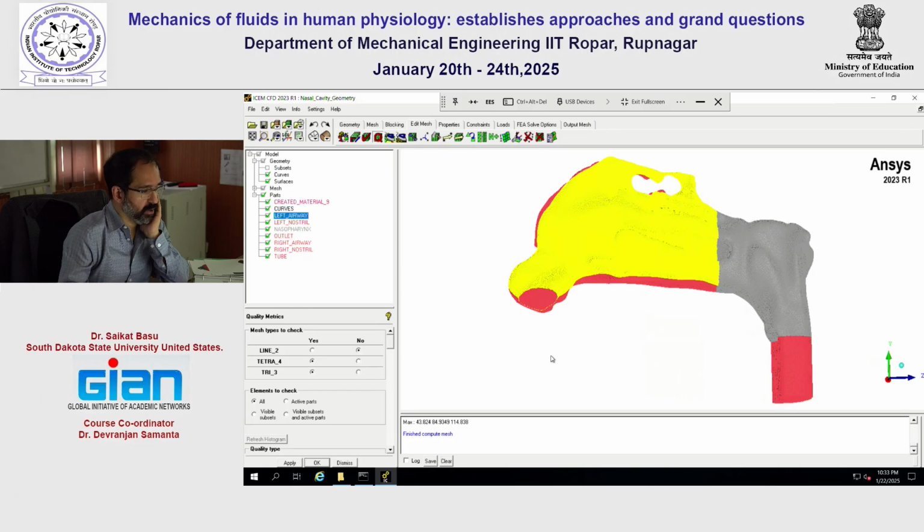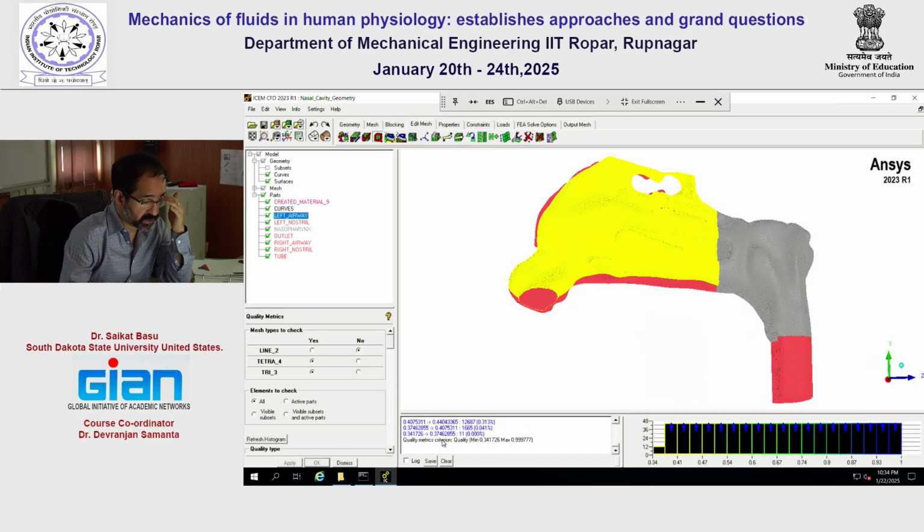Okay, so if I go to this fourth tab under Edit Mesh, display mesh quality and press apply, you'll see that basically they classify the meshed elements in terms of their quality. How do I define quality? It is how smooth the geometry transitions are from one mesh to another. Now, this is fine. The thing that we track is in the worst quality bin, which is the bottommost menu, if the percentage is close to 0%, which it is.